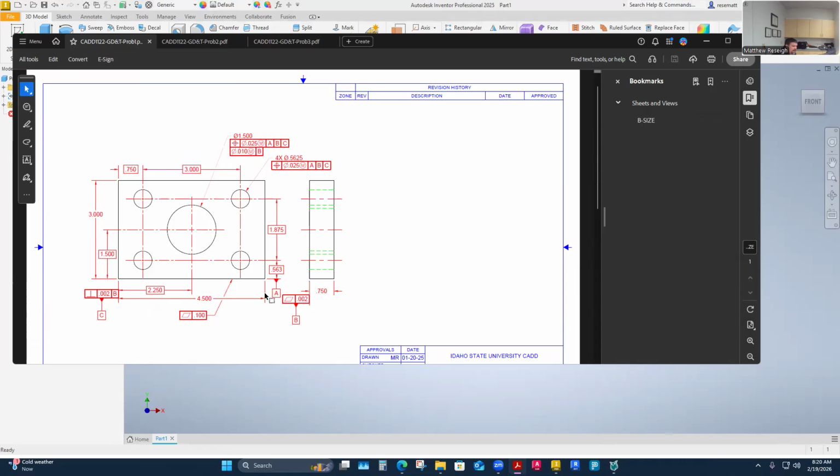This caught my eye right off the bat because I think what I was trying to do is have datum A just be the bottom surface. And this is all just datum surfaces on this. And so it does have three datums, A, B, and C, identified. I just don't love the other thing I don't love, these datums hooked to that feature control frame, because that also, to me, in my little study, means I might be talking about a circular. I'd have to check this.